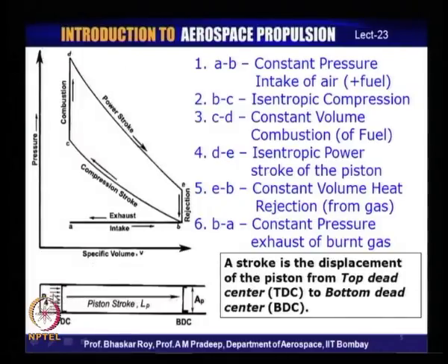Now, this compressed air is then subjected to burning of the fuel. This burning of the fuel in this small space creates even higher pressure and, of course, high temperature. So, this small, highly compressed air, when subjected to high temperature and pressure, then exerts huge pressure backwards onto the piston head, and as a result the piston is forced to move, and that undergoes the process of expansion all the way from D to E. And during that process, the piston head is moving back from TDC all the way back to BDC.